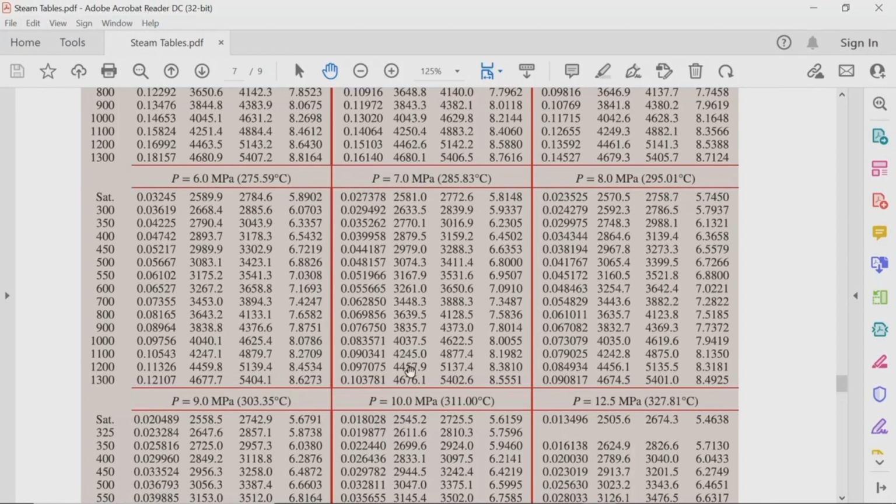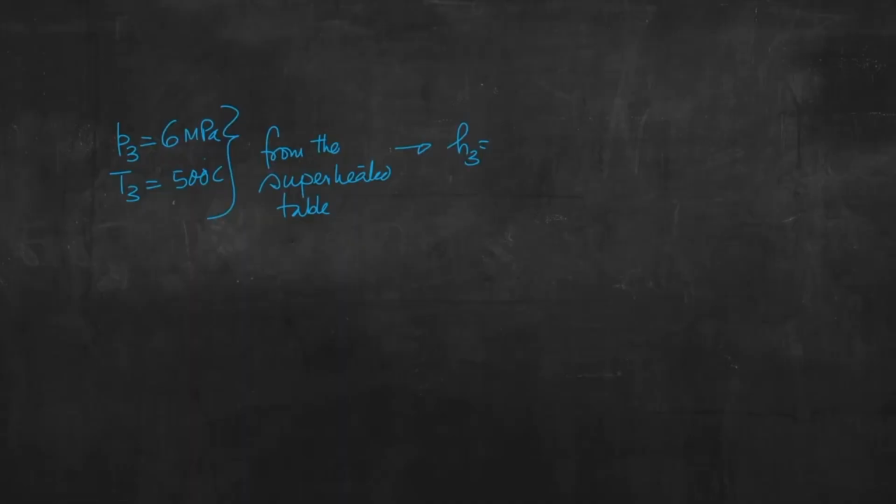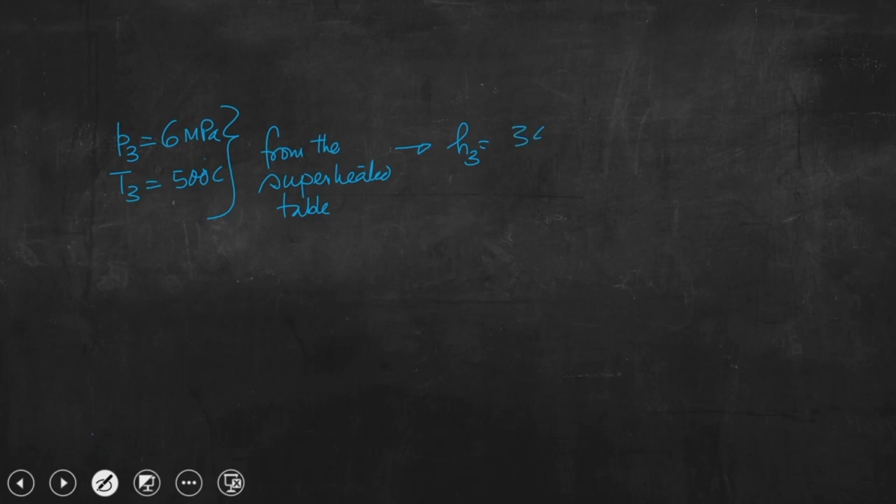So, we can go on, because entropy is also required. Why it is required, I shall explain immediately next to this task. So, I am now going to the slide. What can we calculate? Enthalpy, that is 3423.1 kilojoule per kg, and S3, that is specific entropy, is also 6.8826 kilojoule per kg Kelvin. This we had obtained from the steam table.